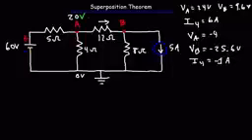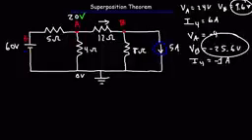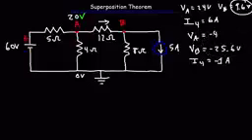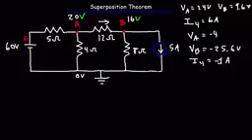The potential at B is going to be the sum of these two. So it's 9.6 plus negative 25.6, which is just 9.6 minus 25.6, and that's going to be 16 volts. But not positive, but negative 16 volts.